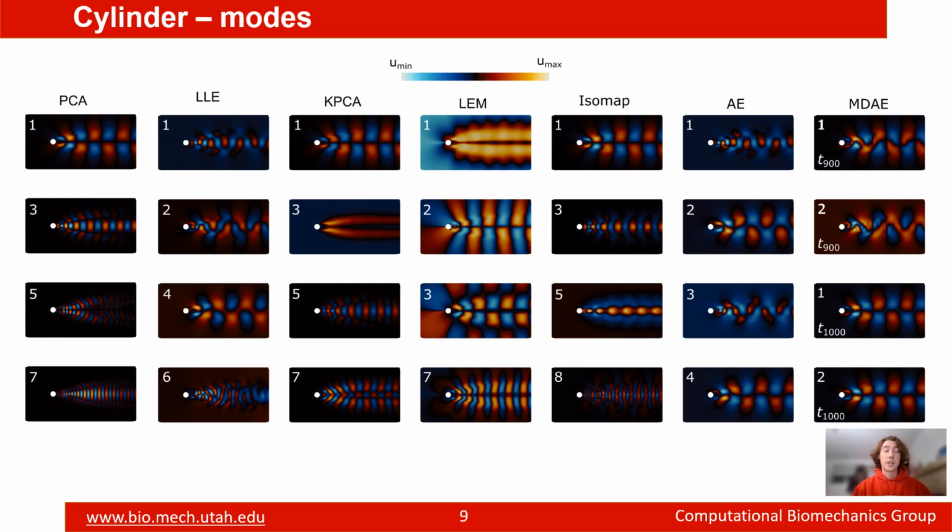Temporal reduction gives us these visual modes that we can try to investigate. Here we see 4 representative modes for the flow over cylinder case for the different methods. We see on the right the mode decomposing autoencoder, that its decomposed fields are time dependent. The numbers refer to the mode number. Smaller numbers mean more important modes in all cases except the autoencoders where the order is arbitrary.